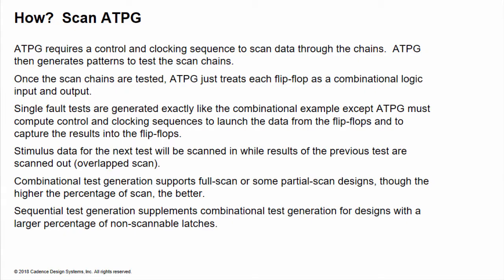We can now proceed with the ATPG loop we discussed earlier for the combinatorial logic tests, with the addition that the test generator must set test control primary inputs and pulse the clocks as required to launch the scan data and launch transitions for dynamic tests and to capture the design response into the observing flops.